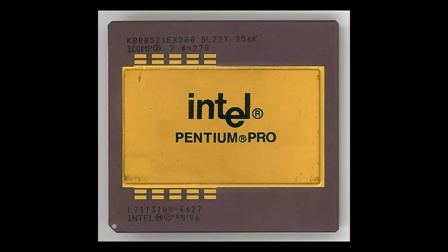It is worth noting that even if the CPUs were only offered with 2.5 and 3.0 ratios, the Socket 8 boards also allowed the use of 2.0 and 3.5 ratios, although only the 200 MHz version could use the 3.5 ratio in a stable way.